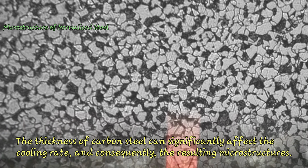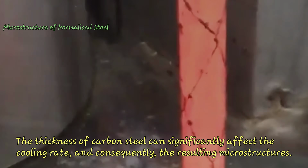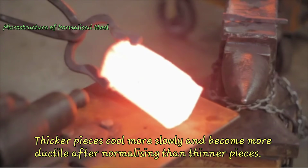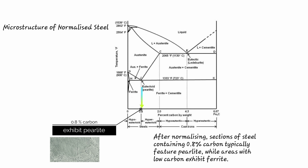Microstructure of normalized steel. The thickness of carbon steel can significantly affect the cooling rate and, consequently, the resulting microstructures. Thicker pieces cool more slowly and become more ductile after normalizing than thinner pieces. After normalizing, sections of steel containing 0.8% carbon typically feature pearlite, while areas with low carbon exhibit ferrite.